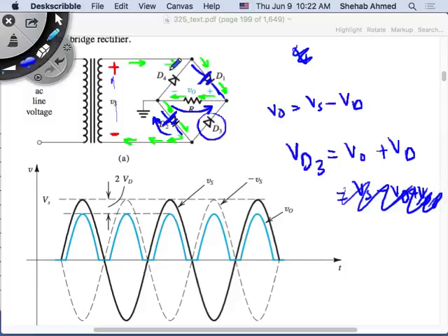Okay, let's see what's happening here. So this is Vs, right? And I'm moving this. This is Vs here, and this is Vs minus. Current is flowing in this direction, so VD will oppose it. So VD is this one. So this is Vs minus VD. This is V output. So Vs here minus VD1, minus V output, minus VD2 equals 0, right? Do you agree?